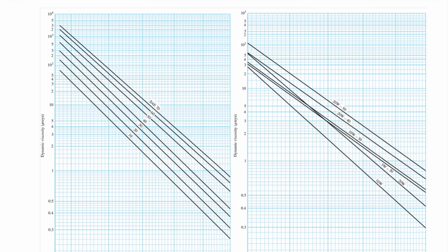I usually get answers about the weight or the viscosity, but really this W actually stands for winter. So when we are in winter conditions, we want the oil to behave with less viscous behavior. Let's think about this. When it's cold outside, the oil in your engine is going to become more viscous, right? As temperature goes down, viscosity of fluids goes up.